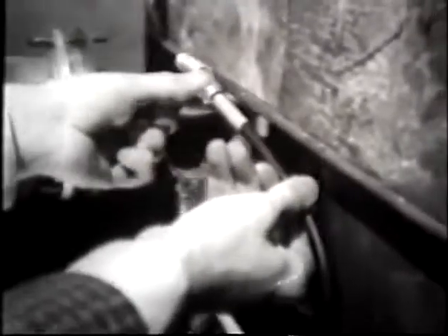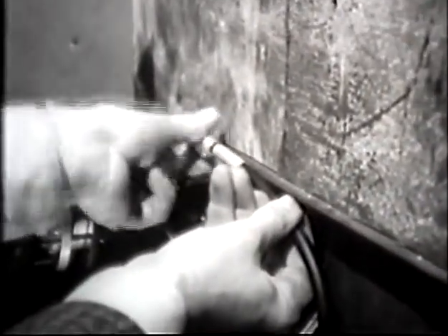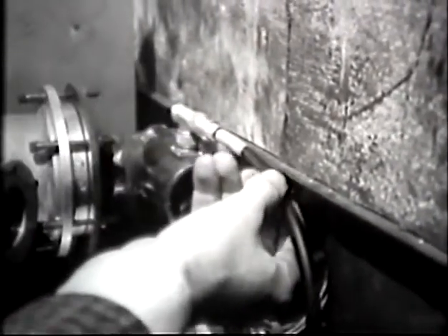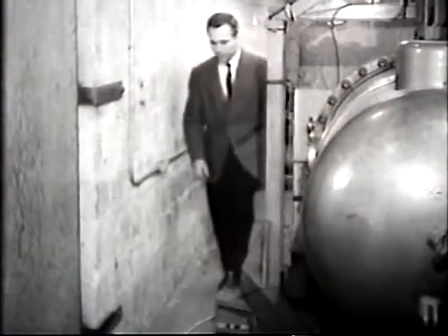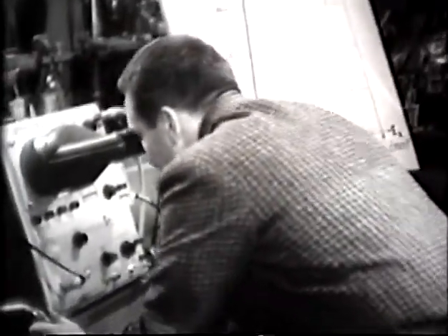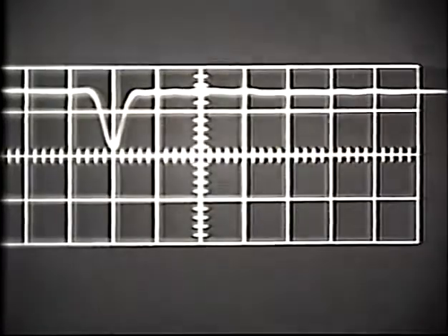Here, I'll connect it to the short tube inside the pipe. Thus, it will carry our start signal to the oscilloscope. This is the signal that tells us when the burst of electrons starts down the long pipe. The signal comes along this cable, and here enters the oscilloscope. I'll switch on the beam. There, you see a signal showing up on the trace.